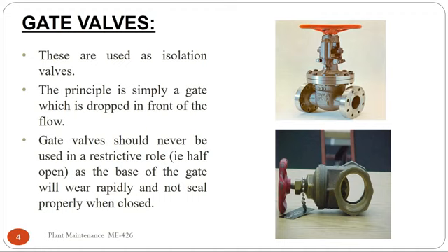There are only one or two persons continuously, as we do not have a full maintenance team, so we have technicians. Technicians do cleaning first of all. This is the main point, because if the threads have dust and dirt, then when you open the handle, there is a chance that after some time the threads will be damaged. So first of all you have to clean the threads, then do greasing and oiling,